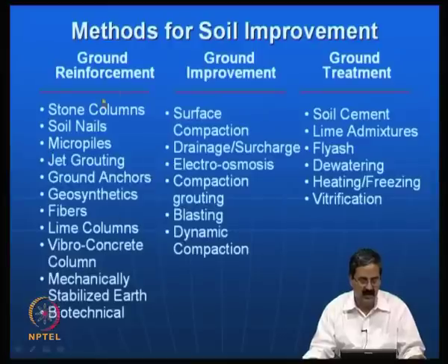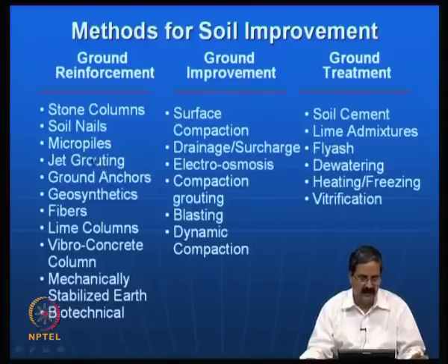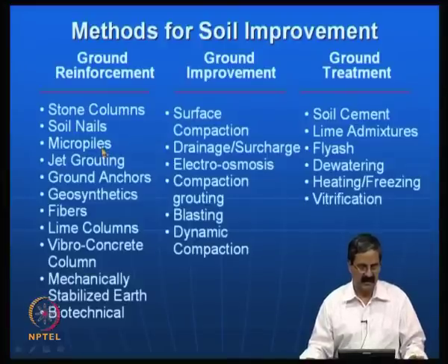Then we have what is called soil nailing. Many of the projects we have been doing use this technique, particularly in the case of excavations where there is a tendency for the soils to slip. Then micro piling is another technique, where if a stability improvement is required, instead of piles we use micro piles, which can be easily driven into the ground.